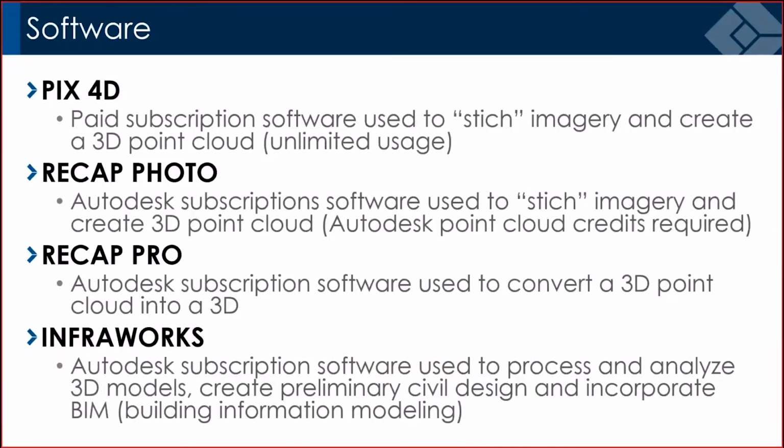Now the software we use to actually process and create our data. Primarily, we run everything through Pix4D. So if we're doing a map or an aerial image, or we're doing 3D modeling, this is a paid subscription that we use. It will essentially stitch the imagery together and create a 3D point cloud for us. The common file you're going to see is the Recap. Recap, again, that's going to be when we go from point A to point C, Recap's always going to be our point B. Recap Pro and Recap Photo will help process and stitch the data together as well.